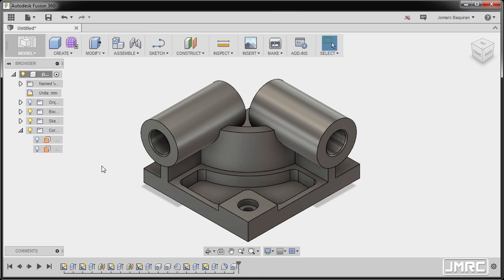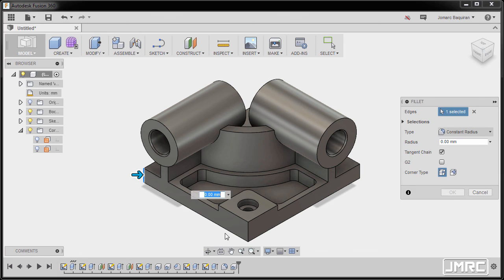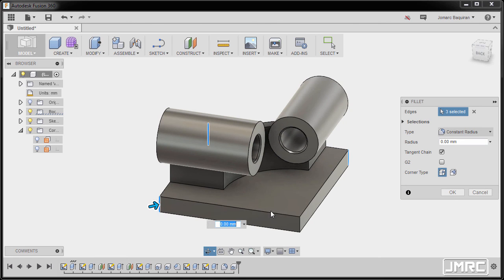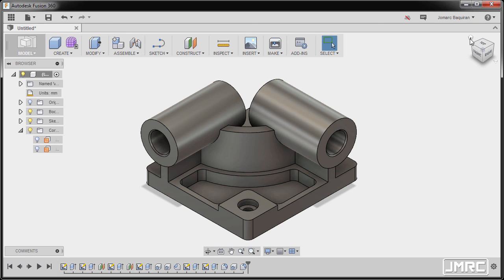Now I'm going to grab our fillet tool, pressing F, selecting this edge, and finally this edge. Going to home view. For the radius, I'm going to key in 10 and hit OK. So congratulations for completing this part model, which came from the CSWP-CORE exam.